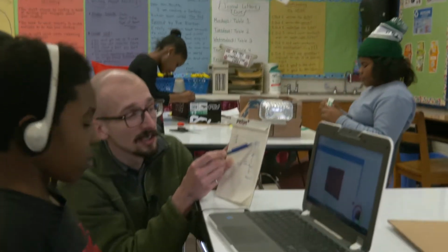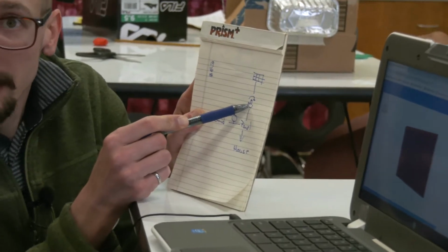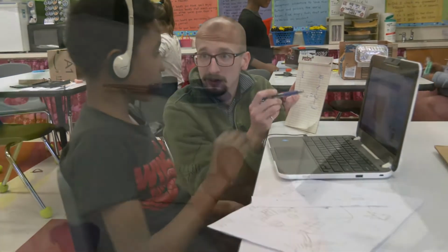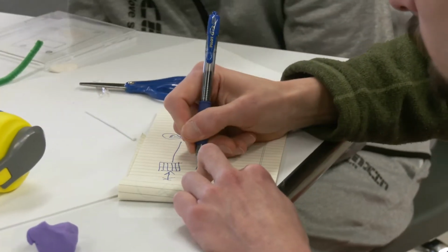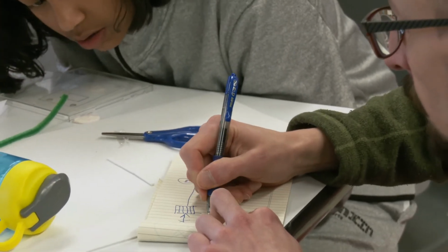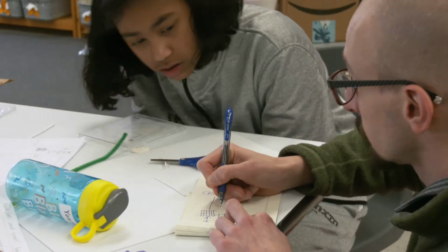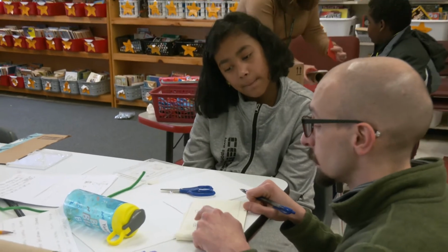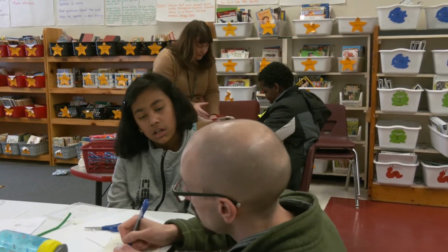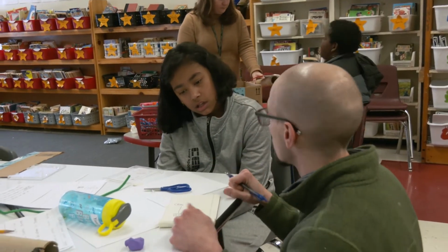The panels, which hit the inverter, which goes to our power panel. And then the rest of the house on this side, we've got the grid over here and an electric meter in between. You've got all the major parts. We'll have a generator here that is also hooked up to our panel, but here in between, we have what's called an ATS. So that if this panel ever senses that it doesn't have power coming from here, it immediately switches over to the generator power.